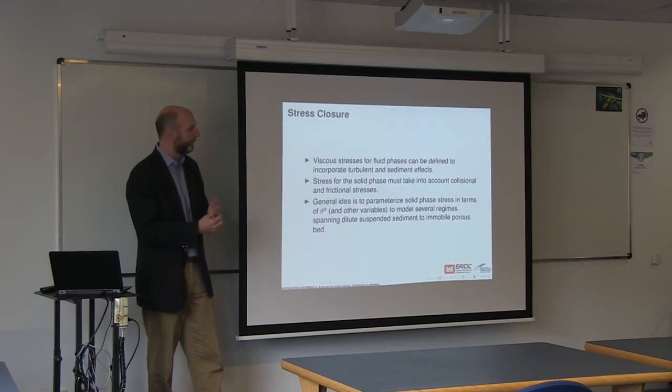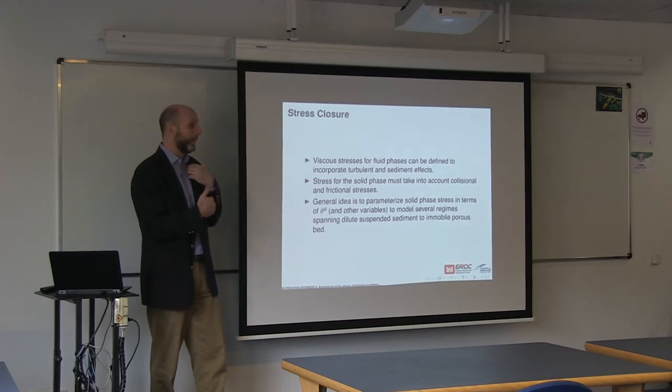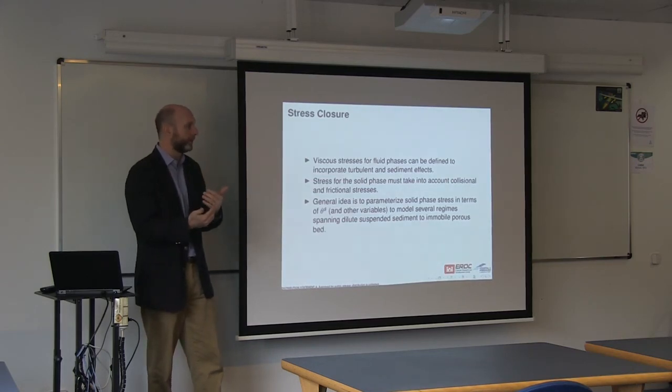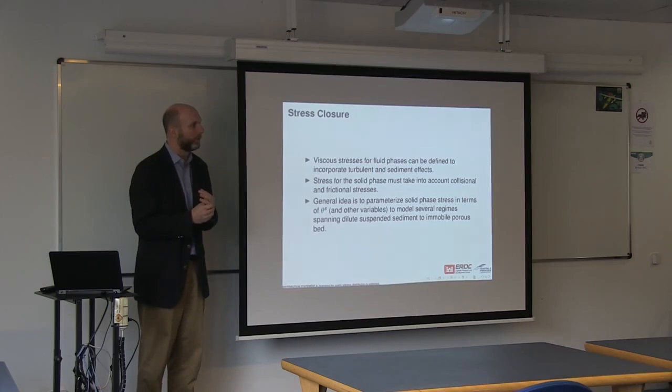My gut feeling is that the immersed boundary method, even though the one that we're using is clearly lower order, may actually be helping stabilize the partitioned FSI simulation in that case, because it's less sensitive to the motion of the boundary. It smears it out a little bit, and so you get more stable computations of drag and lift. So that's why you're using it. Yeah, but we'd like to get the SBM method working and look at some of the other approaches, obviously. It would give us the provable higher order accuracy.